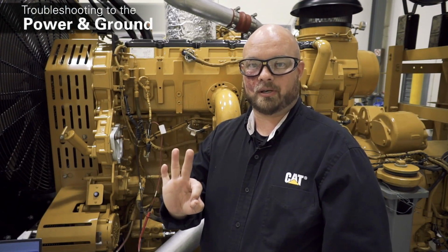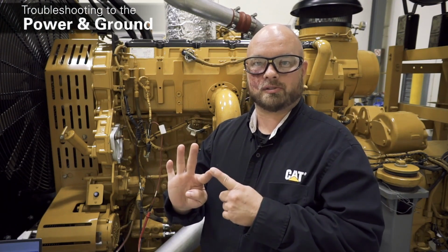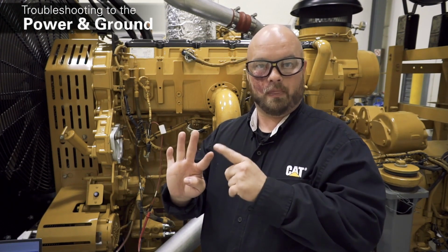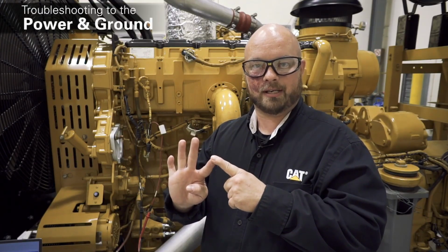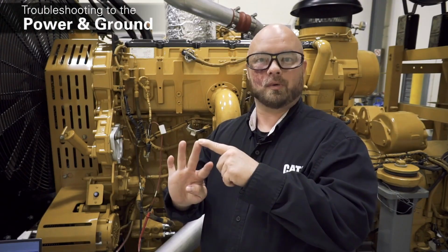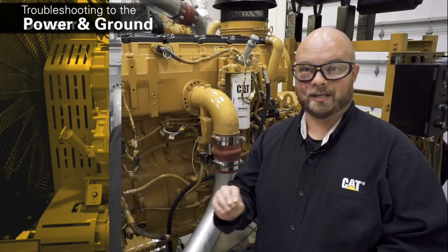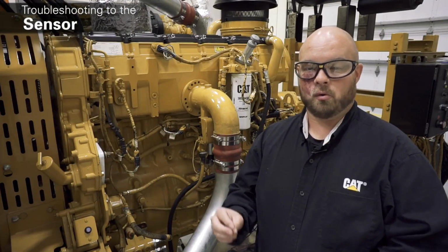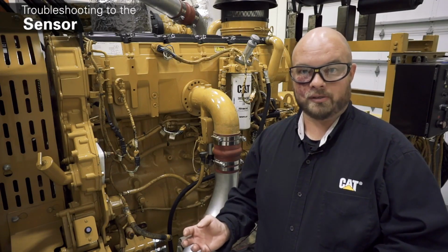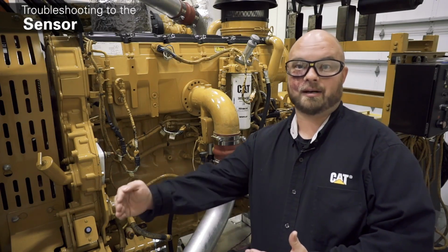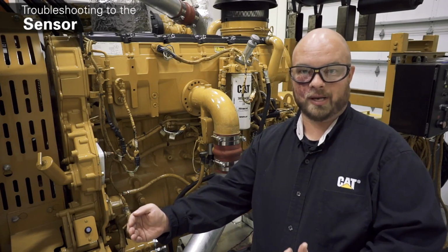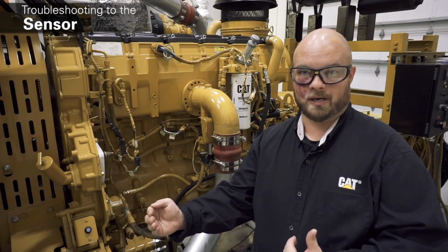It also does something else for us. We're gonna create a short circuit condition and try to flip this code, and that's gonna tell us something also. The B wire that we just validated, we can now use as a ground to short out our C wire, which is the next thing that we're gonna troubleshoot. We can easily validate at this point whether or not the sensor is the root cause of the problem. The way we're gonna do that is take the sensor out of the equation, set the opposite condition of the code that we have and see how the system responds, okay?